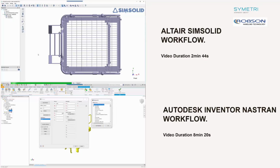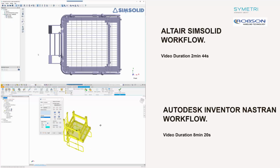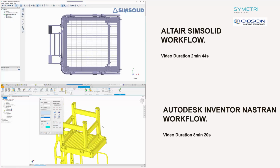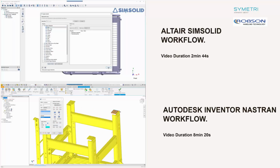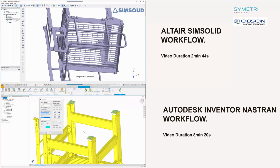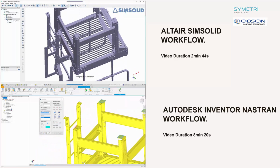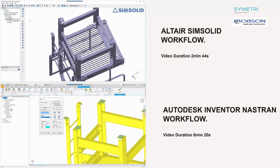We go through our normal steps of going from left to right within the Inventor Nastran menu to set up our model. We're now going to apply a constraint within Inventor Nastran. Within SimSolid, we're currently applying the material. It has already done the connections for us, and we're going to set up the structural linear analysis in SimSolid. At this stage, while we're applying constraints within Nastran, we're doing the exact same step in SimSolid.